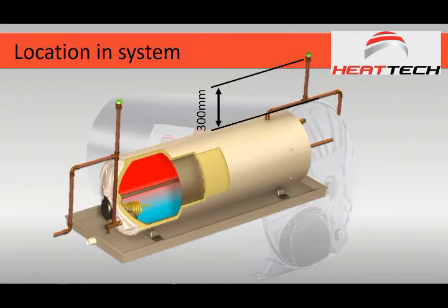Some manufacturers, and you know this useless bit of information as well, go and ask your manufacturer who produces the vacuum breakers, at what vacuum does your vacuum breaker open up? I can tell you there are even some on the market that are so fine-tuned that they are able to open up at 0.1 kPa of pressure. But that's a bit more useless information.